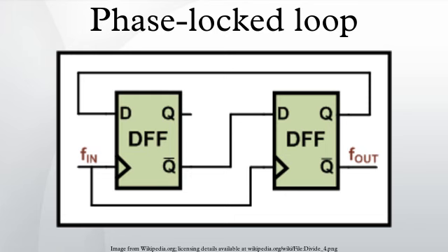The second common consideration is limiting the amount of reference frequency energy appearing at the phase detector output that is then applied to the VCO control input. This frequency modulates the VCO and produces FM sidebands commonly called reference spurs. The low-pass characteristic of this block can be used to attenuate this energy, but at times a band reject notch may also be useful. The design of this block can be dominated by either of these considerations, or can be a complex process juggling the interactions of the two.